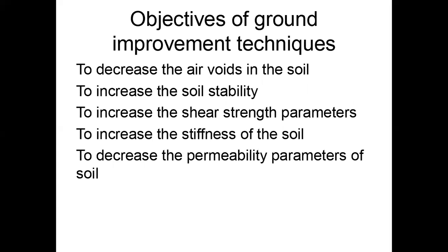While we are providing loads, the structure will be affected, and the foundation, that is beneath the ground level, will collapse because of the presence of air voids in the soil.